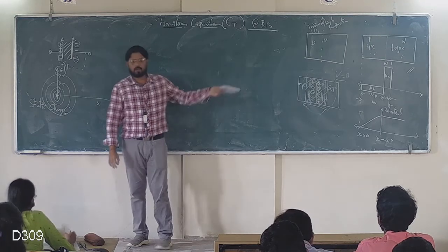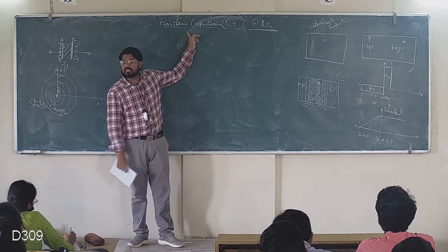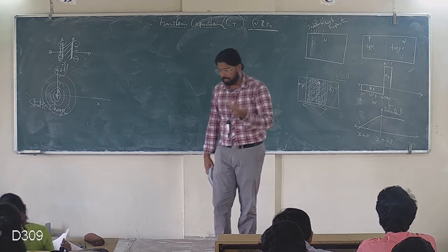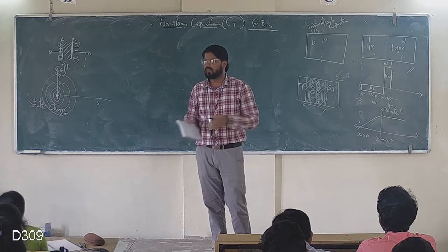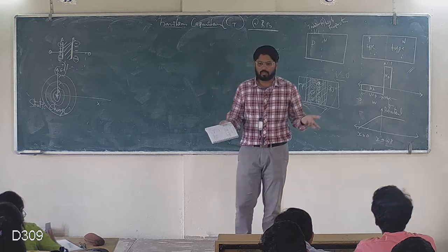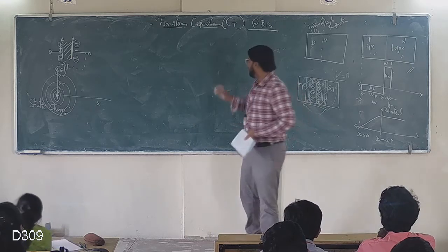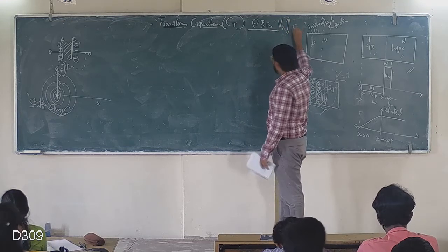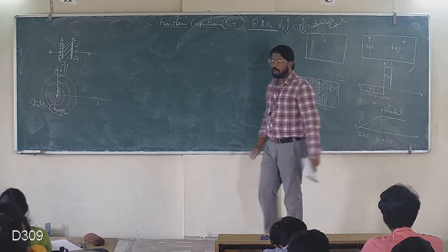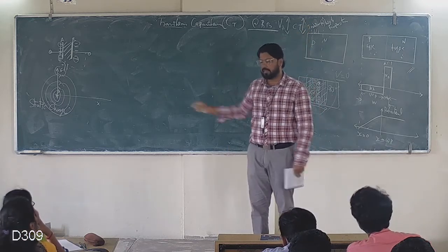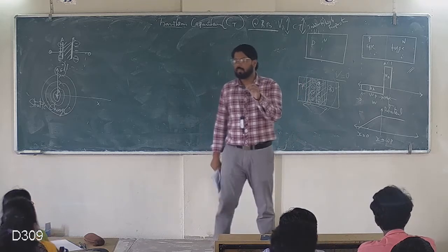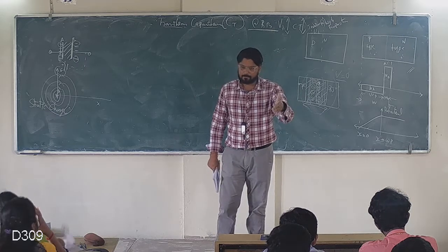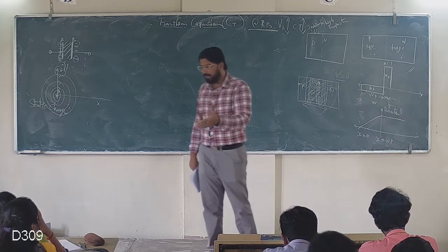Okay, now come to the point of understanding transition capacitance. Why transition capacitance? Because the reverse voltage keeps changing. If I increase the voltage, what happens to my CT? If I decrease the voltage, what happens to my CT? What increases or decreases? Reverse voltage. Whether it increases or decreases, that is what we are here to study. What is transition capacitance? It is the capacitance effect at the junction that exists during reverse bias.